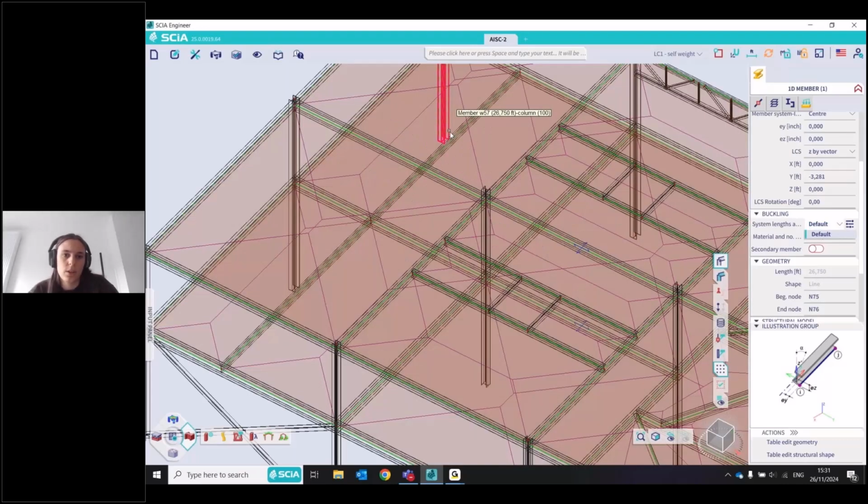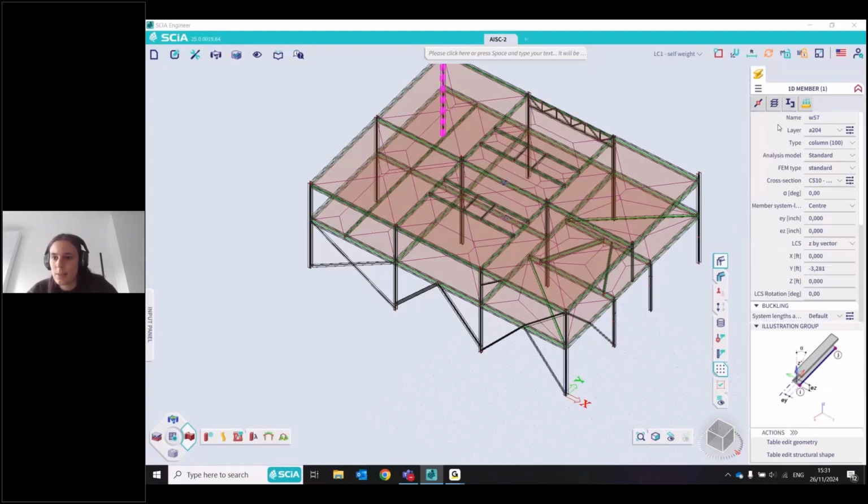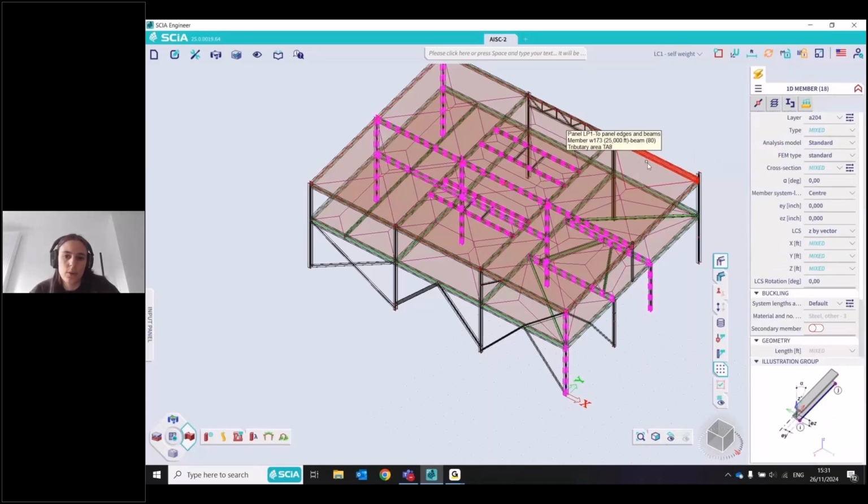So they cannot share buckling settings because they don't have the same amount of points arriving on them. If you want to quickly select all the ones which could share a buckling system, there is this option here, steel, and you can see it's divided in 3 regions. If I click expand selection, based on that, I can select all the elements which could share a buckling system.